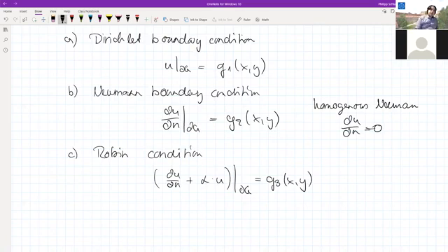But one needs to be a bit careful here, because sometimes in CFD codes with zero gradients or even stress-free boundary conditions, a slightly different thing is meant. Then it's typically the sum of the normal stresses that are 0, and the normal stresses are the pressure plus the velocity gradients. But typically, yes, it would be a gradient boundary condition. That's a homogeneous Neumann condition. And the no-slip boundary condition is a homogeneous Dirichlet condition.